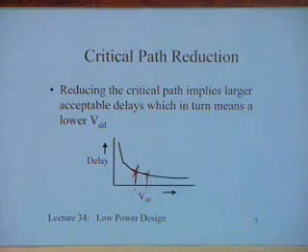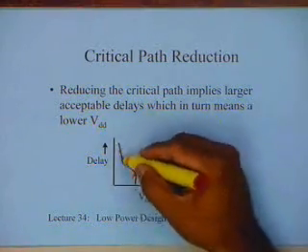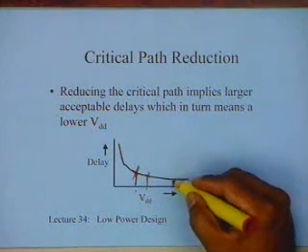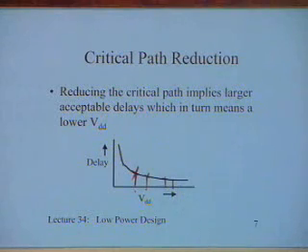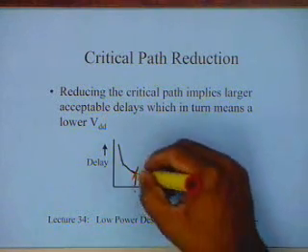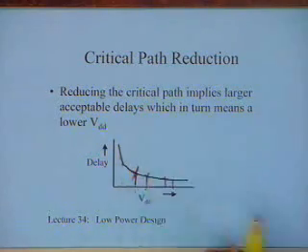Of course, it is important to know at which part of this curve you are operating, because there is a saturation effect. So, if you are operating at this level, the change is not going to bring you very much. Depending on which level you are operating at, for example at this level again, the VDD that you can reduce will be very small. So depending upon which part of the curve you are operating, you can reduce the VDD sometimes substantially, sometimes not by that much, and you can reduce the power that is consumed.